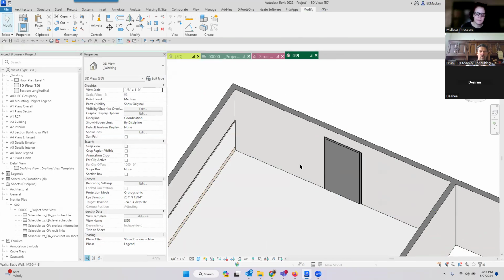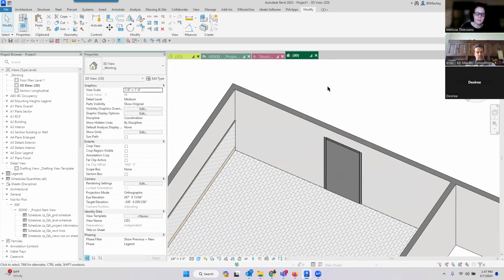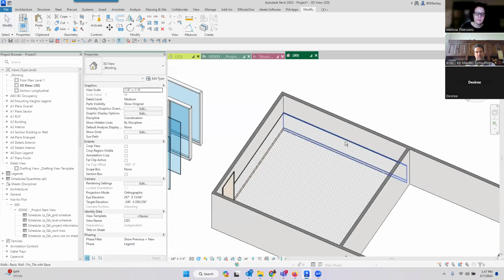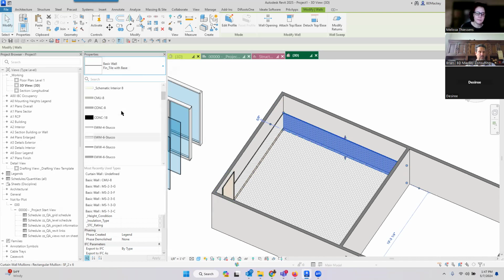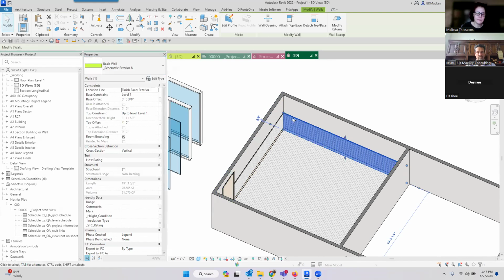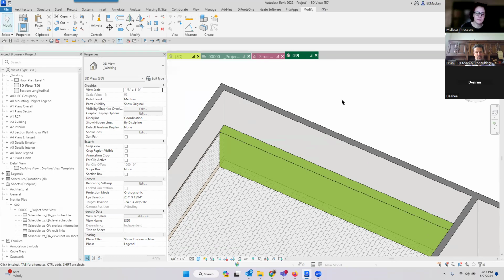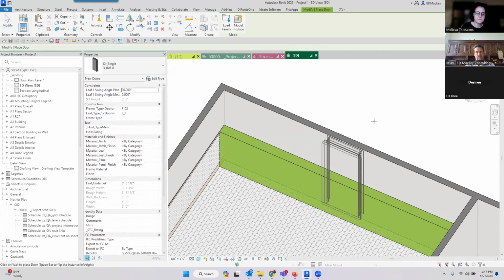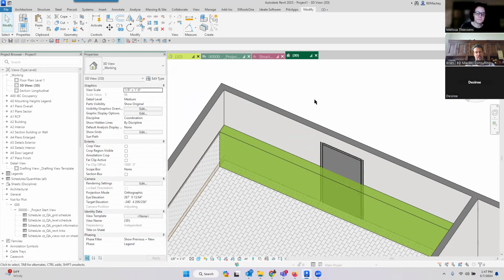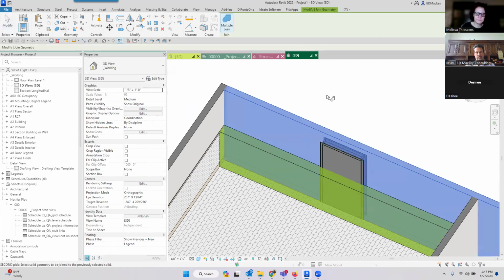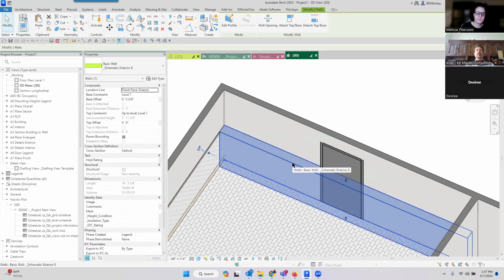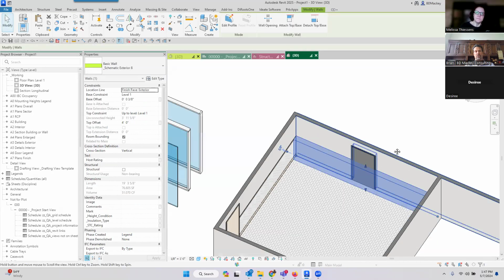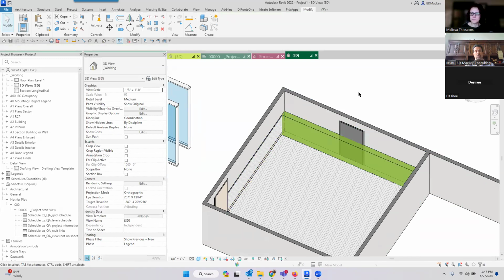If I undo and undo, and change that wall to a wall that is not vertically compound, and then I place my door in this one, and then I do the join tool, you can't even swap it. So if I would have started with this wall, that's why I was redrawing it. If you had a wall that was that way, the join breaks.